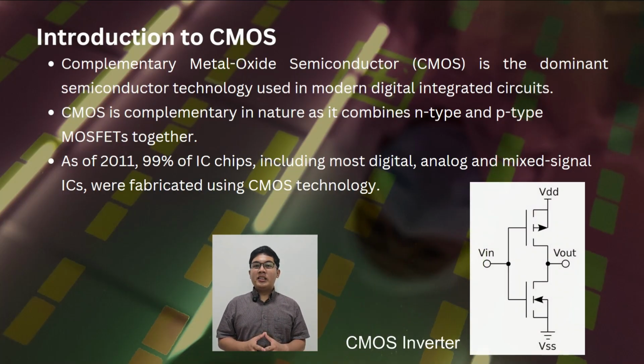The simplest application of CMOS technology is actually in this simple circuit here called a CMOS inverter. It acts like a NOT gate, where when you put 1 inside it, the output will be 0. This happens because when a gate voltage is applied, aka at the input, the NMOS is biased while the PMOS is unbiased, causing the ground to short to the output, yielding a 0, and vice versa happens when no gate voltage is applied.